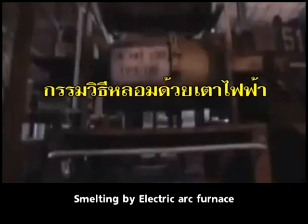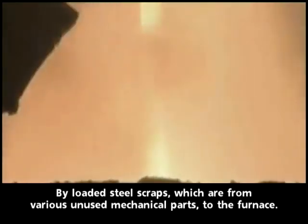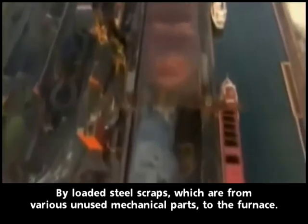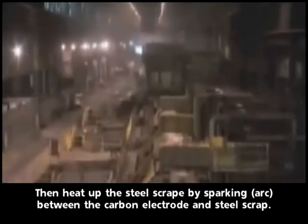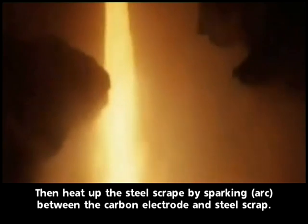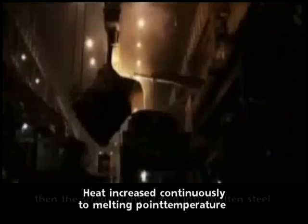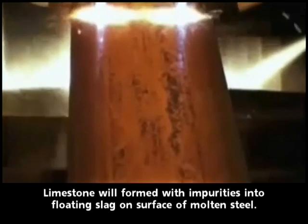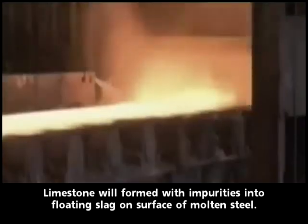Smelting by electric arc furnace. This process is currently very famous. Steel scraps, which come from various unused mechanical parts, are loaded into the furnace. Then the steel scrap is heated by sparking between the carbon electrode and the steel scrap. Heat increases continuously to the melting point temperature, then the scrap transforms into molten steel. Limestone forms with impurities into floating slag on the surface of the molten steel.